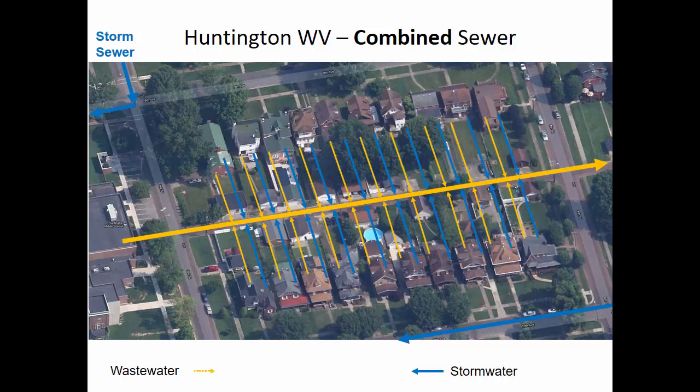And according to EPA regulations, there's only a couple times per year they're allowed to have a combined sewer overflow. I mean, it would be better if it never happened at all, but there's so many old municipalities on the east coast of the United States that have inadequately sized combined sewers that it's inevitable occasionally on a rainy day the wastewater stormwater mix is going to get into the creek. So that's sometimes abbreviated as CSO, a combined sewer overflow.